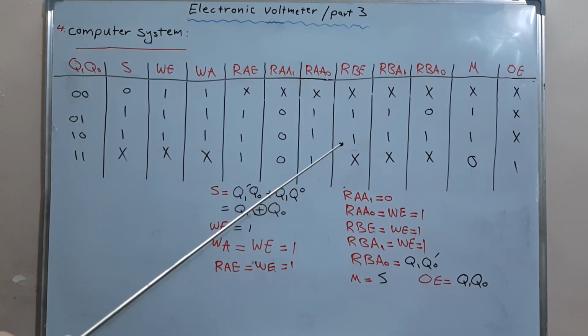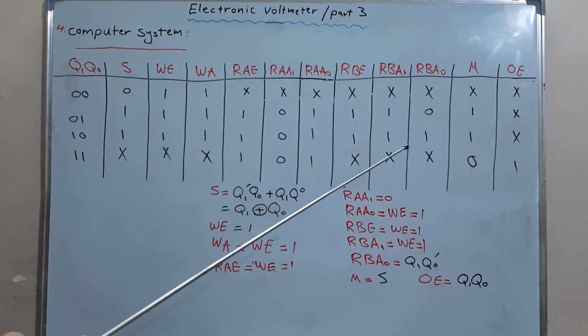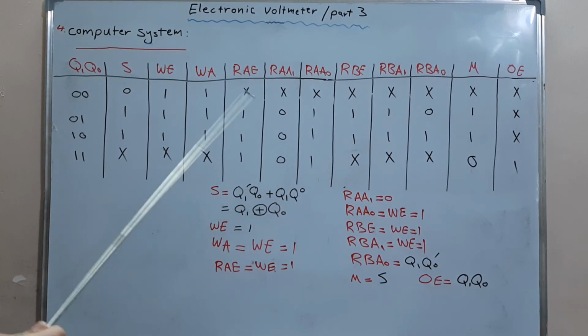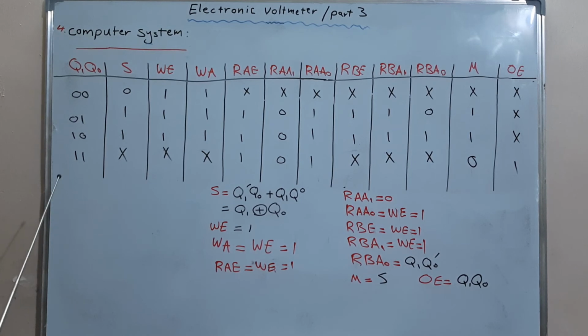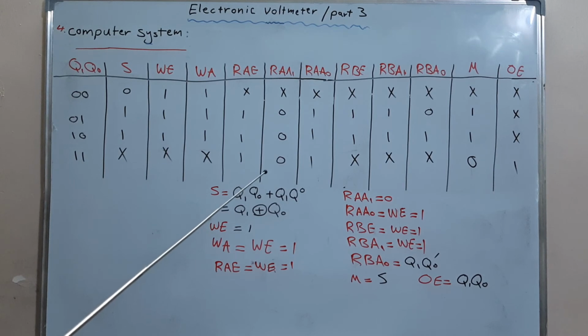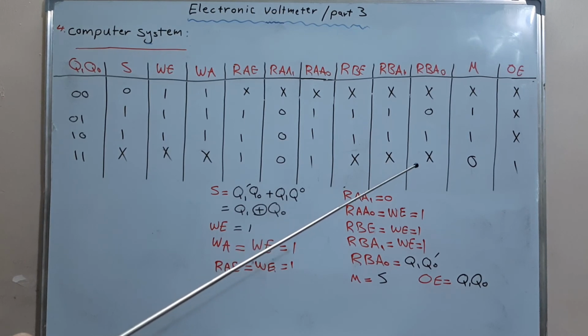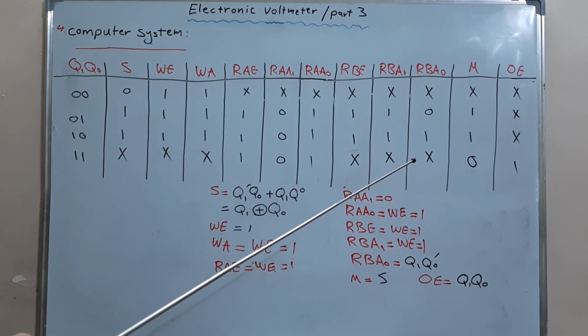In the third state, the decoders of reading A and B are both enabled, and the values in the second and fourth location will be read through port A and B respectively, multiplied by each other and returned back to the same location. And during the last state, the decoder of reading A will be enabled, and the value in the second location of the register file will be read through port A, pass through the passer circuit, and then output from our data path.